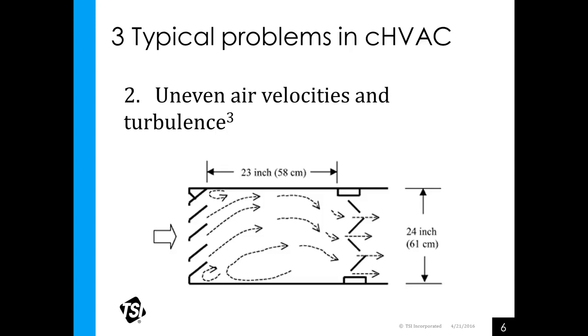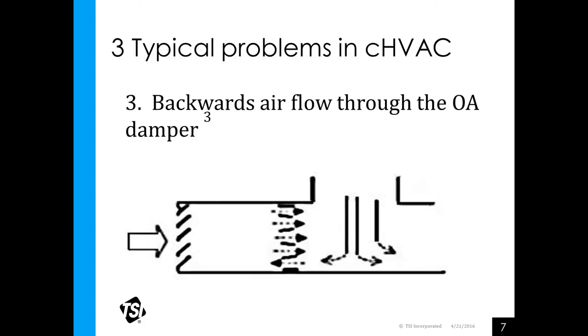Even in critical HVAC systems, outside air flow rate measurements really are most critical when the dampers are mostly closed and the minimum amount of air is being supplied to the building. So again, in the outliers of environmental control, you've got to make sure that your settings are proper. A lot of engineering systems take a look in the duct. You might or might not see flow straightening devices used, but there only needs to be a consistent relationship between the outside airflow rate and the output signal of the HVAC sensor system to be working properly.